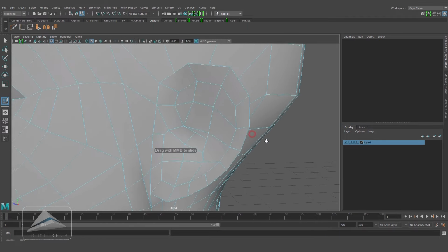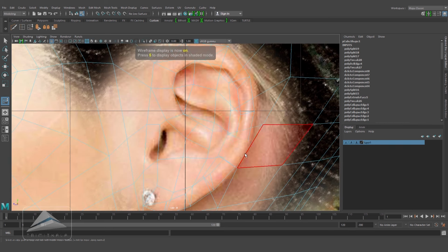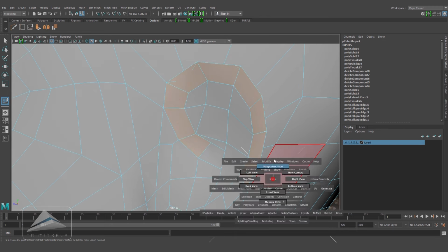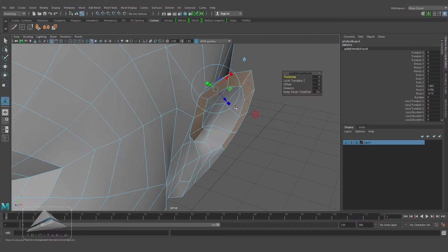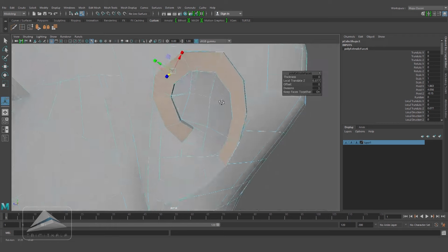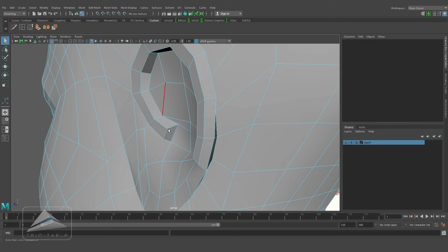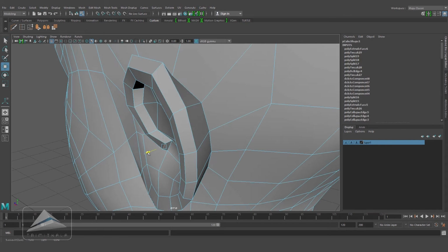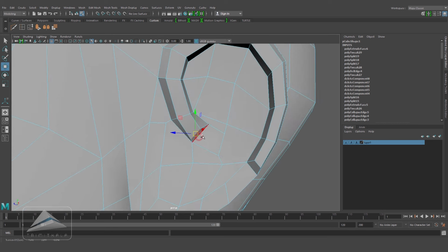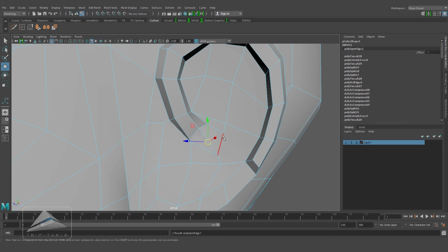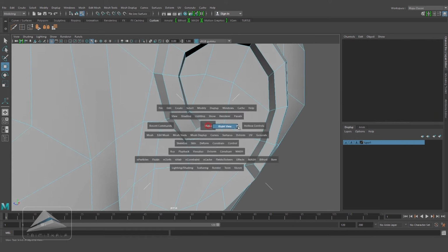Now I am going to select the faces of the helix, and you can see this is the area, this is the origin of the helix. So from there I am selecting the faces. I am leaving the last face to spin my edge and extrude it and pull it out, scaling it down, and similarly at the origin of it I am pushing it inside and selecting that edge. I am spinning it. I am using the keyboard shortcut Ctrl Alt and forward arrow and adjust the vertices.